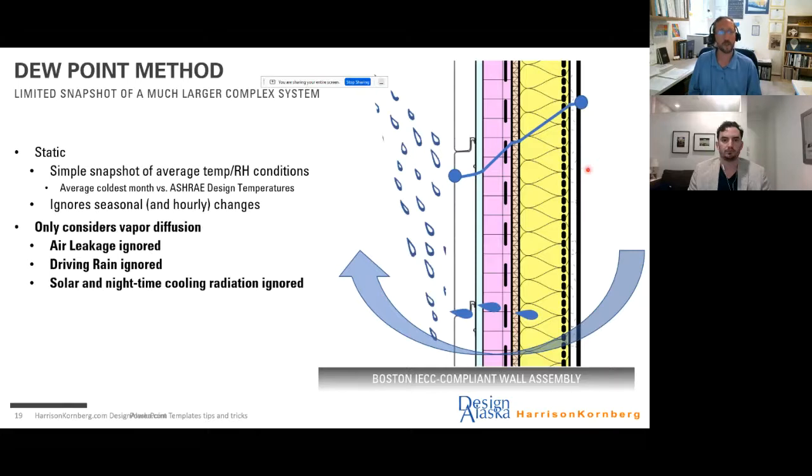Much greater contribution, especially in cold climates, is exfiltrating air, the vapor-laden air from the inside finding its way through the wall assemblies, through gaps and cracks, and every hole in that vapor barrier. Screwing the gypsum board to the wall creates a hole in our air barrier layer, and it's bringing that moist air into this cold wall cavity where it can find that plywood condensing surface.